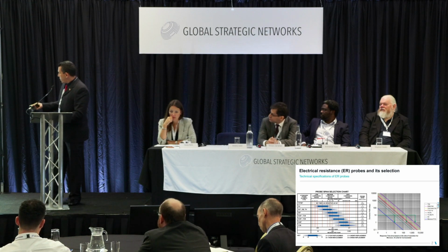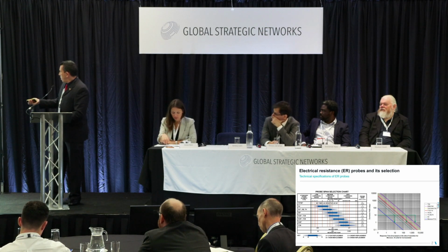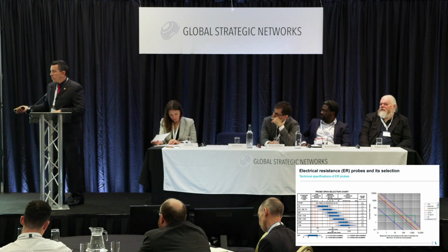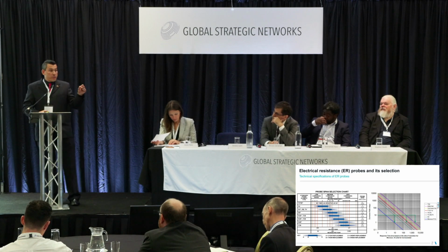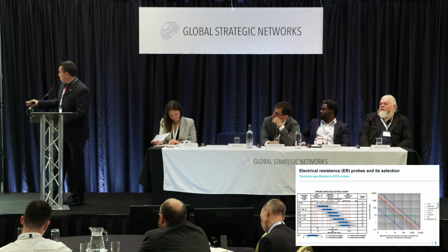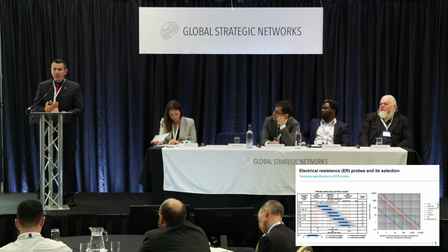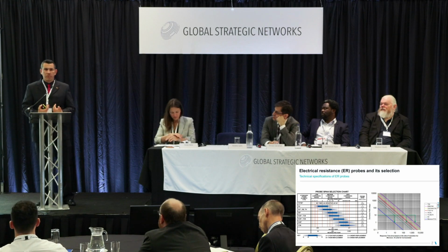For the state-of-the-art corrosion probes, micro core, you can have a response time of 10 hours. If you go to another one, the F40 type, you can have more than 110 hours waiting time for a stable reading. And if you go to the thickest one, that can last 2 or 3 years, it will take more than 1 week to have a stable reading. So this is why you need to have more information about the process and what you want to get from this corrosion probe.